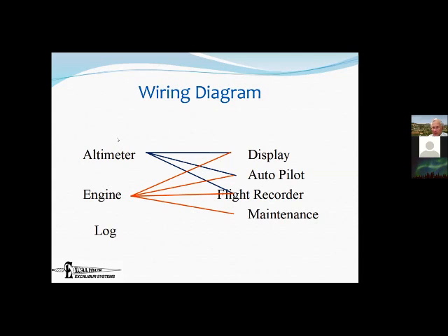It is not legal under 429 to have more than 1 transmitter on a bus, which simplifies things a great deal because there are really 2 issues from a technical point of view that you have to make decisions on when you're creating a digital bus. The one issue is how to make sure you don't have multiple devices transmitting simultaneously. And 429 handles that very easily. You're only allowed to have 1. That's just the rule, 1 transmitter on a bus.